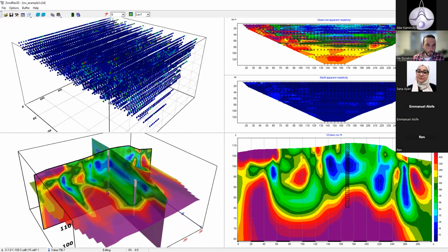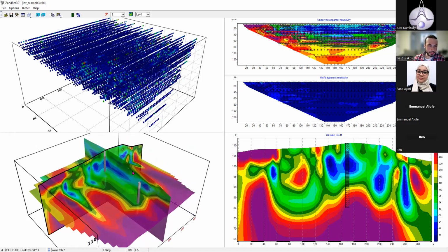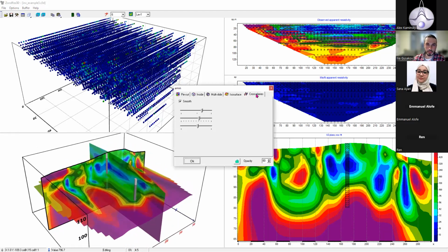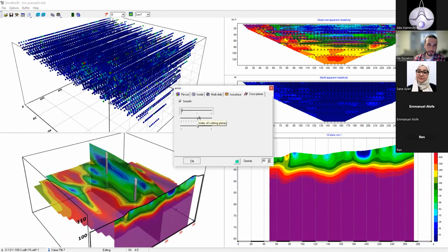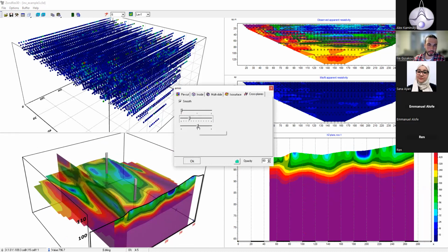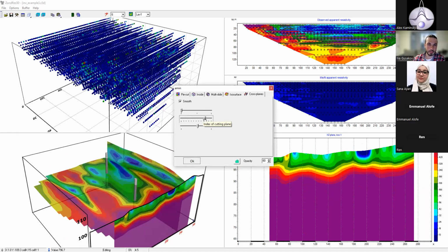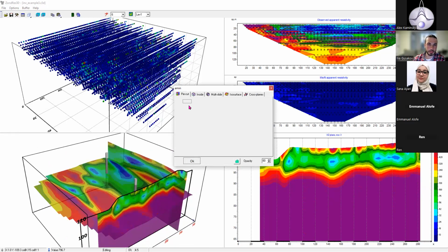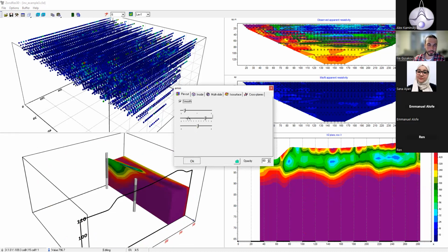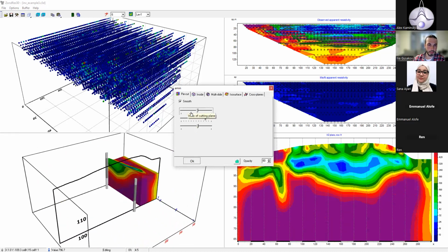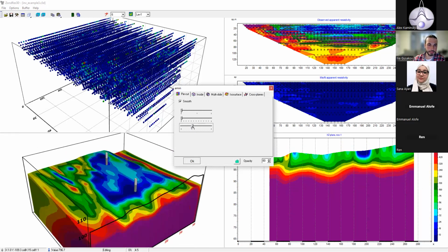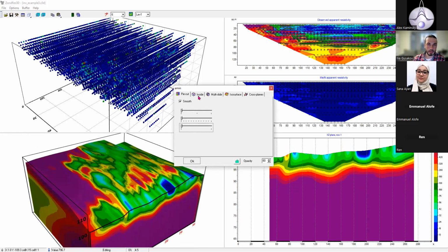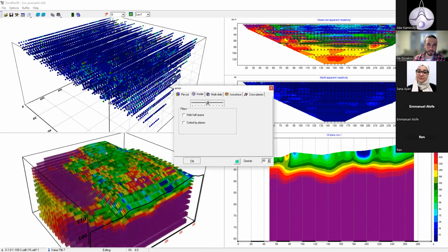There are several ways to visualize your data in 3D. So this way to visualize is called the cross planes, where the data are plotted using 3 orthogonal planes like this. Another way is called a pie cut, where you can just cut this 3D volume in the 3 directions, like so. Next is the inside.